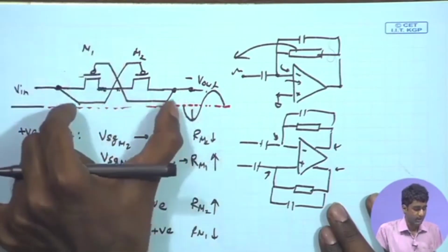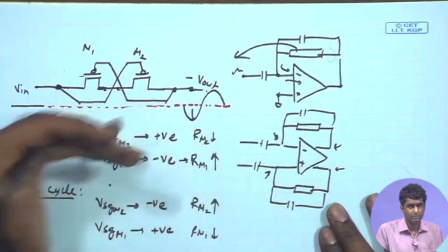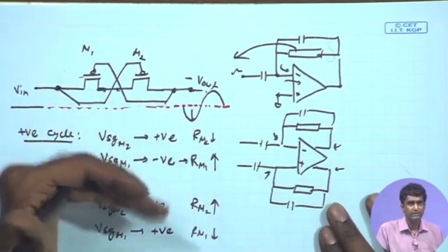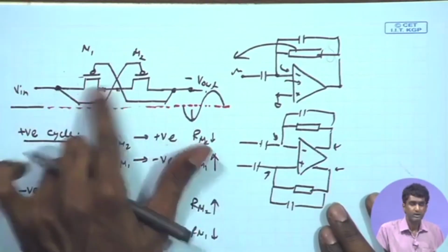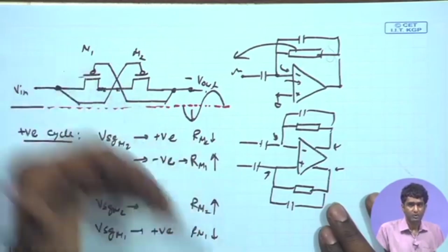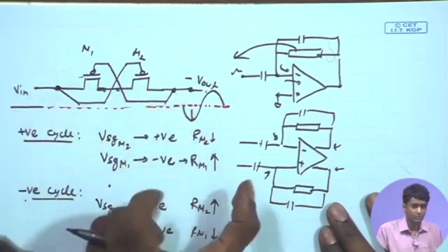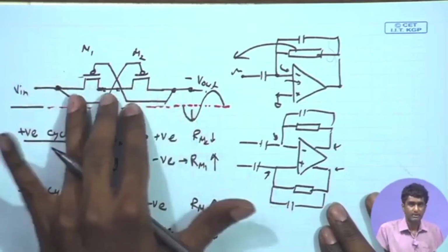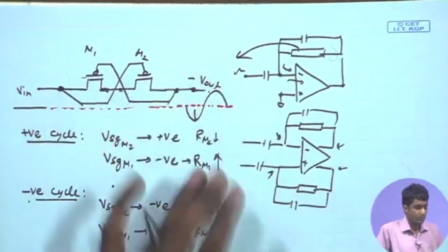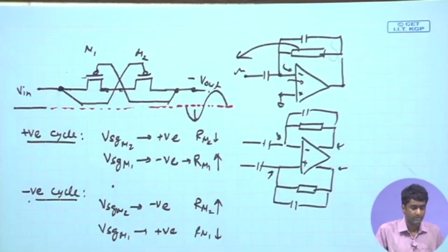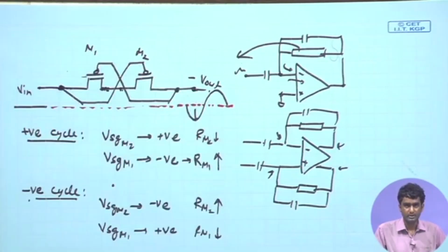In the silicon we have the option of tuning and matching it to the required value, because in simulation you may be expecting some values, but in the silicon you can end up having very different values because of a small change in the VT. Over time the resistance can also change exponentially because of the subthreshold operation, and hence you can end up having a very different R value and a very different frequency spectrum on the lower side for our amplifier, which is not desirable. Therefore, we will see how to incorporate some tuning option in this circuit.